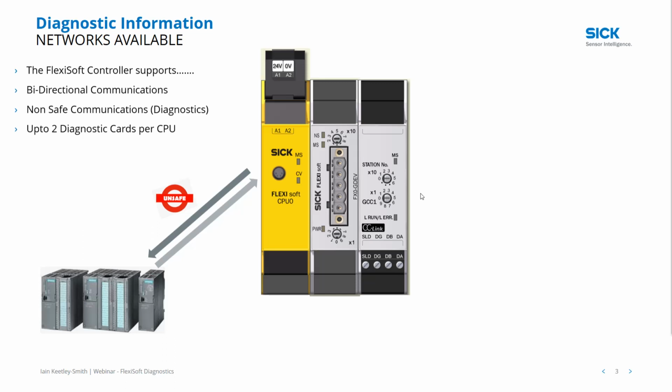And on that presentation it was stated that you can have up to 12 cards attached onto the side of a CPU. I just want to make a point here that the diagnostic cards do not count as part of those 12 cards. So even though we've got 2 diagnostic cards here, we could still have 12 safety cards attached onto the side of that. So that is the capability that we have.